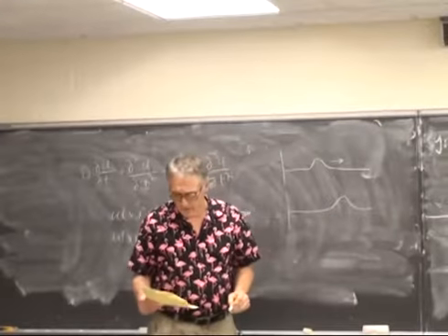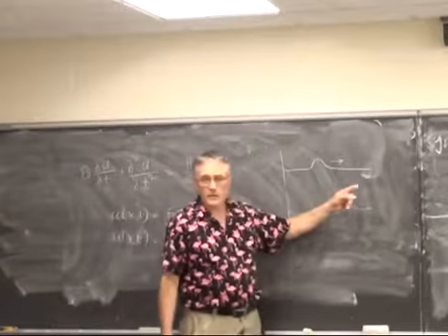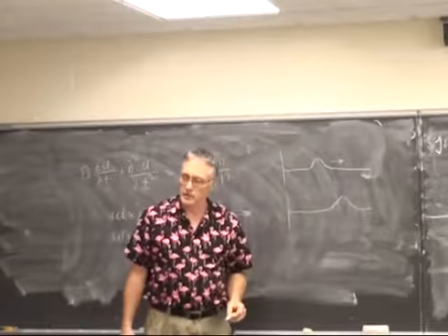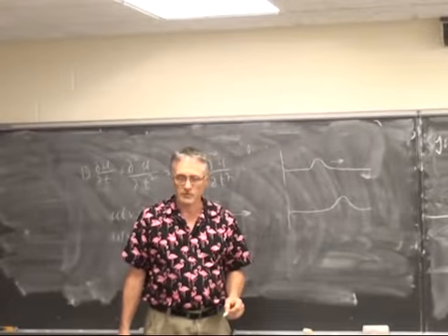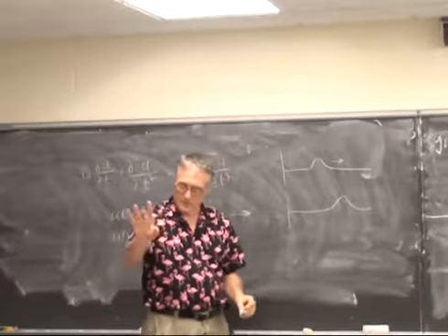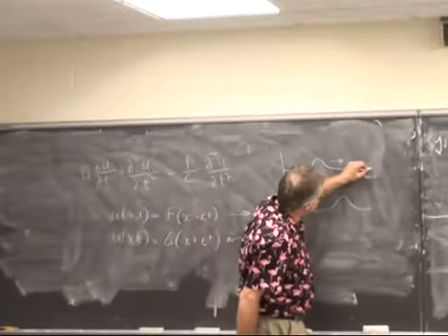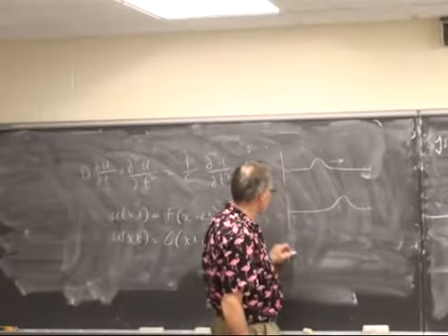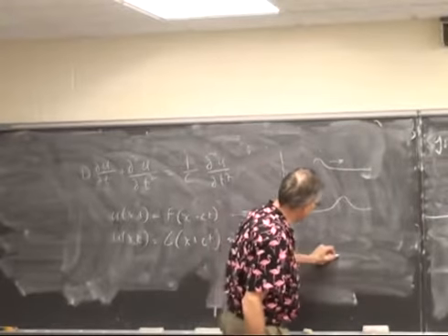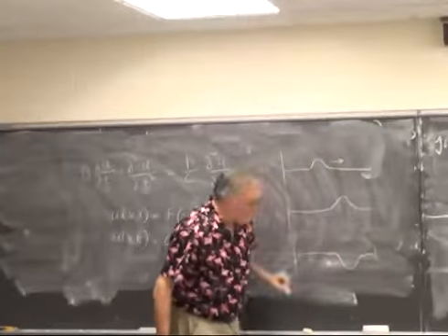That means that all you have to do to simulate a string is to have a shift register. And the differential equation is equivalent to a shift register as long as you get the boundary conditions right. And that is that at the ends here, when this hits the end, if it's a fixed end, it gets reflected back, inverted, of course, now traveling this way.